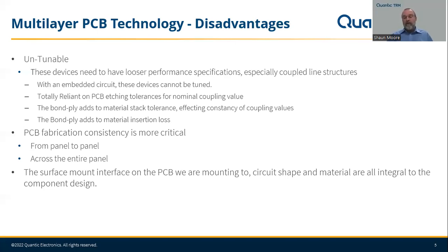The interlayer registration becomes very critical, especially from an RF standpoint. The relationship of the active vias and the ground vias, you form virtual walls within these sorts of structures, and having that whole interplay work, you just need to be very, very cognizant of the tolerances involved as you're doing the design. Can be very successful.